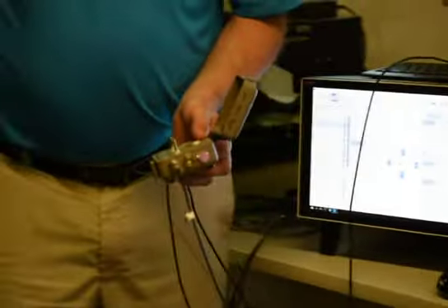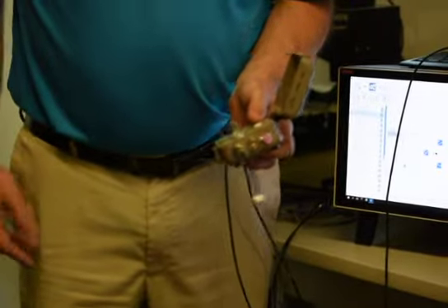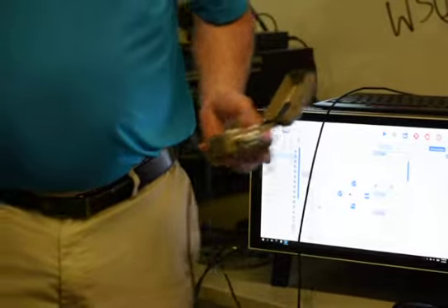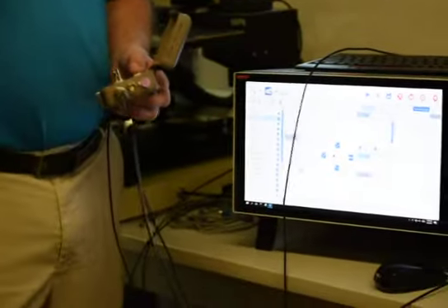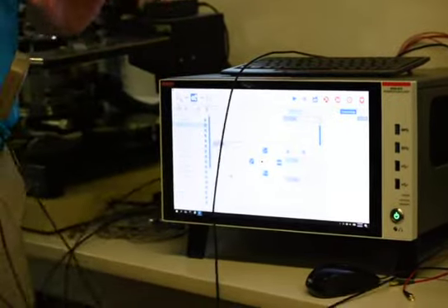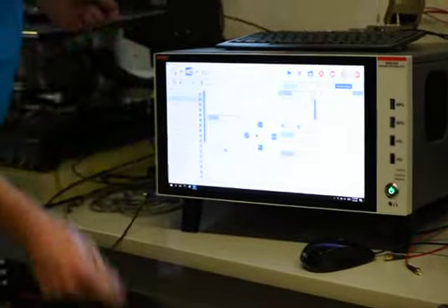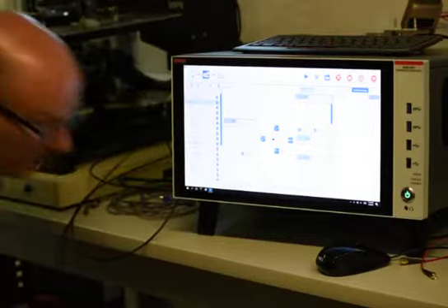Or you can also put the working center there. I could. But there's the bulk. The only thing you're going to measure in the bulk is capacitance, right? So typically you'll measure from gate to bulk to get capacitance. But right now we're doing a family of curves. We don't need it. So there's our connections to our device. This is my SMU4 here. I'm going to use that.